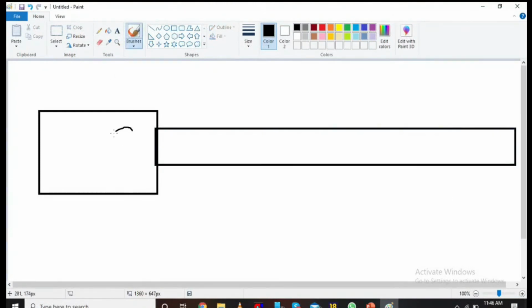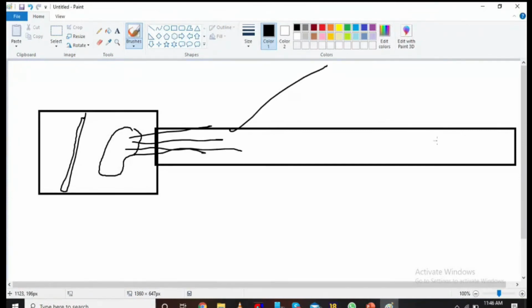But the purpose of the fan, with the air that is touching and coming from the coil, is to push the air. It is to discharge air to the rooms. So positive static of the fan will be more. Negative static will be less, because automatically from the room, once the volume is filled, the air will go to the return grills and the return duct and come back. So negative static will be there, but it will be very marginal.